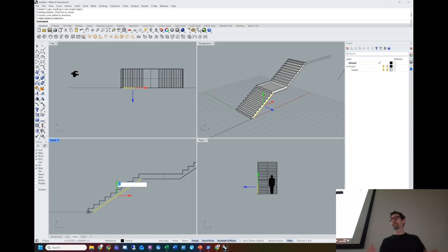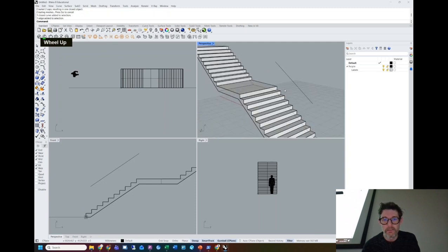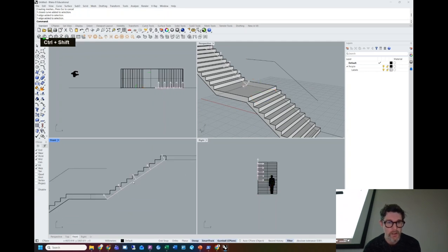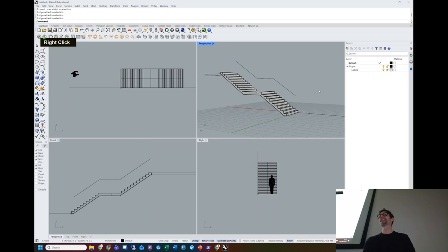I think these ones are a little bit low. Maybe they're 1050 or something like that. Let's say we want 1,100 millimeters from, interestingly, the stair, not from the bottom of that. So now I have to add a little bit in my mind for this distance to the stair. So I'm going to call it 1,200, just for the sake of speed. And now I've got a handrail floating in the air. Nice so far. I'm going to do exactly the same here. Hold down Alt, move it up, make a copy, 1,200. Exactly the same here. Hold down Alt, make a copy, go up 1,200. And now I've got the beginnings of a really lovely handrail.